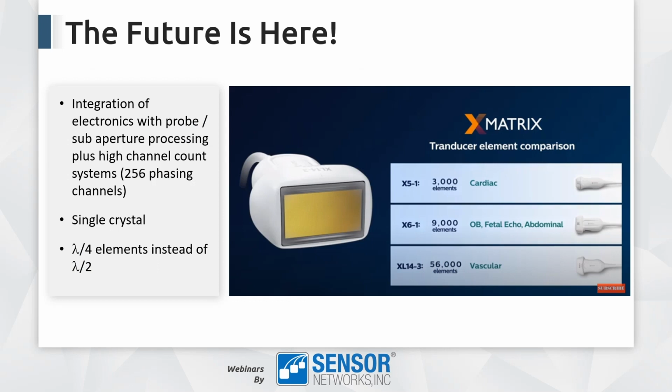But you see that medically speaking, they're going to very, very high element counts. And the way that they're doing that is by integrating electronics with the probe using what they call sub-aperture processing. So they actually have phased array processing in the probe handle that does some sort of pre-focusing for groups of elements, and then they're connected to high channel count systems with 256 and more phasing channels.